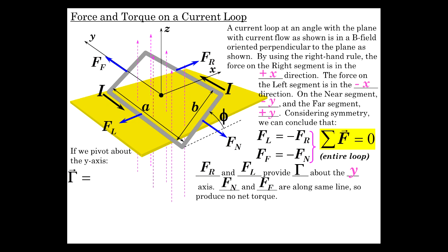What's the torque? Well, the torque is provided by the moment arm on the right side times this force. And down here for this one, it's the distance from the y-axis down to the inclined plane, and then the force intersects there. So from the halfway point, the distance from here down to the plane.